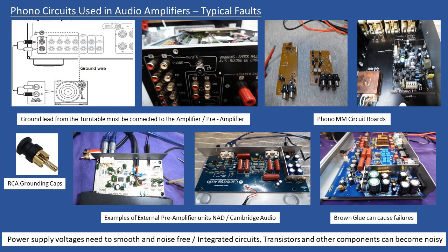You can do that with the capacitors. Alright, so in terms of electrical noise, just to finish off on this, most important, make sure that your connections are good and that your ground connection is made. Your signal wires are good, you don't have a broken negative or positive signal lead.